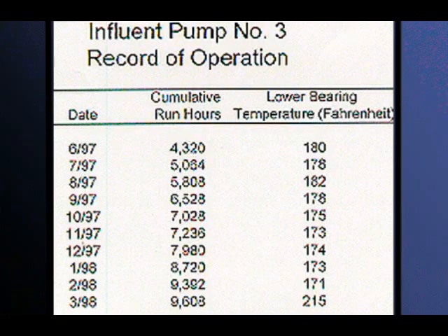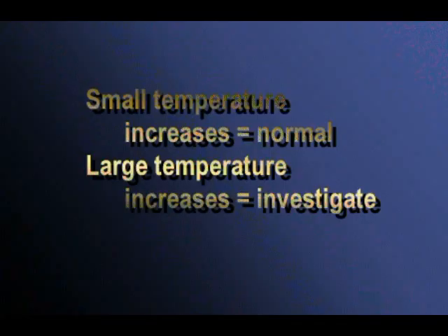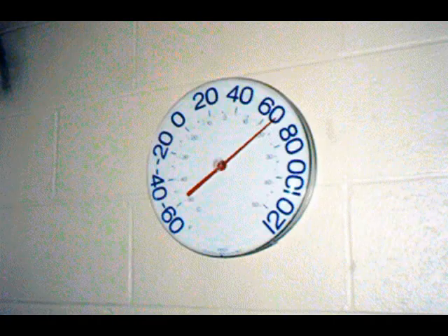Any significant increase in temperatures for a given bearing should be investigated. However, a very small gradual increase can be expected as part of the normal aging of equipment. Also, keep in mind that increases in air temperature will also produce an increased bearing temperature. Therefore, record air temperature as well.